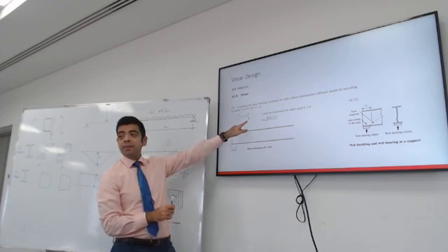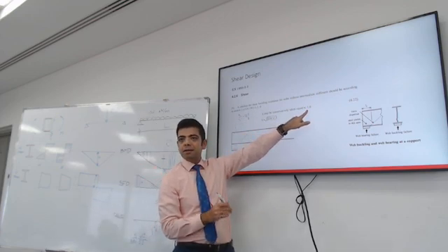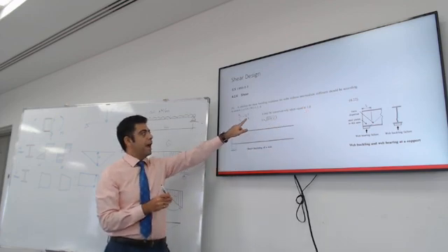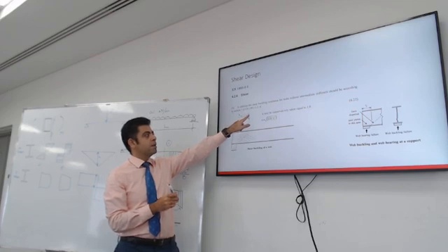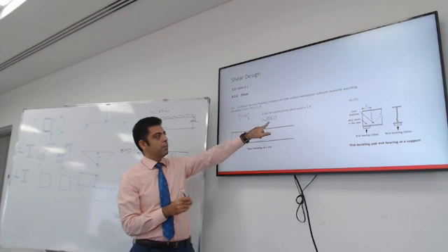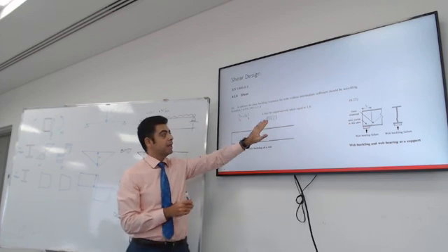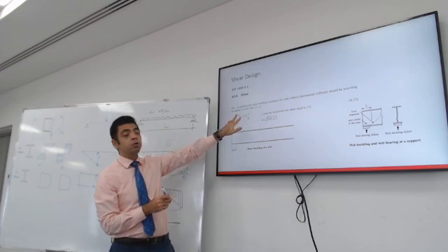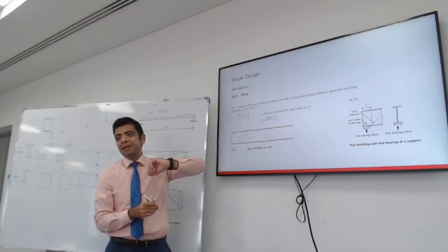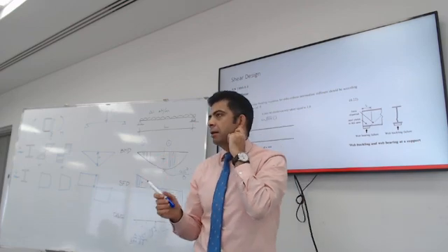The factor at the bottom is suggested to be taken as 1 as a conservative way, and the strain that you design for is from this equation. So knowing the grade of steel, you can get this number and just make sure that you don't exceed this limitation. All right? And that's the main design part.